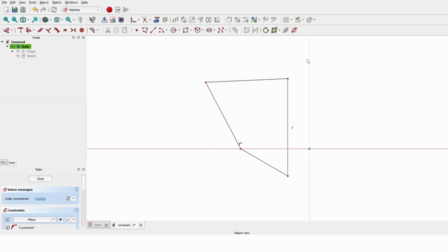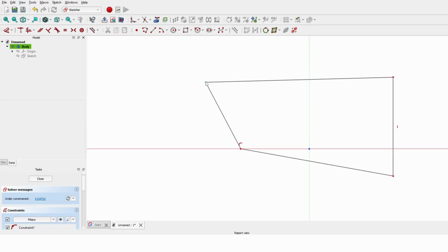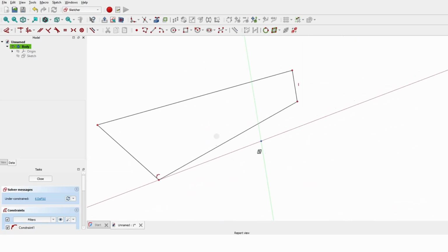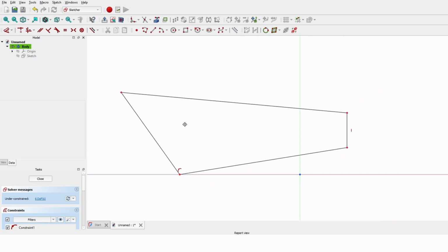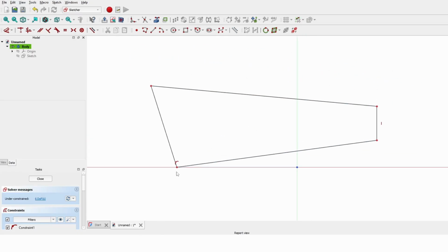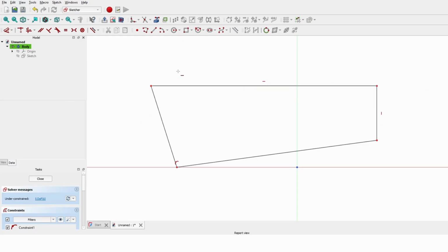So now we have the ability to make 2D shapes, but now we want some precision because we are making engineering projects, even if it may be DIY. Okay, so now we want to make a box or something that is pretty regular and not random like this. One of the first things that we could do is to make all of these sort of parallel or perpendicular to each other. So we can use this here, constrain horizontal or vertical. Constrain horizontal means that it will make lines horizontal to our screen, and constrain vertical is the other way, vertical.